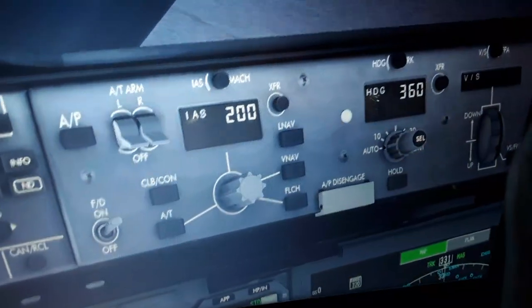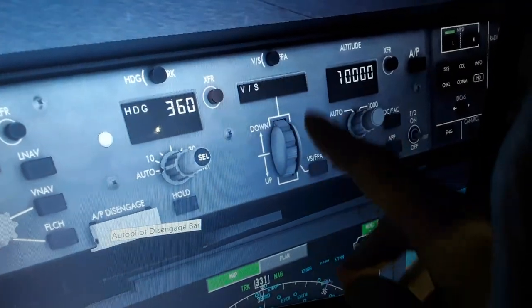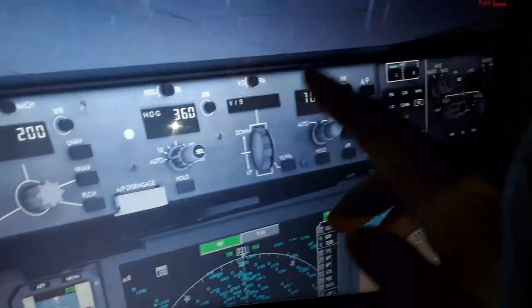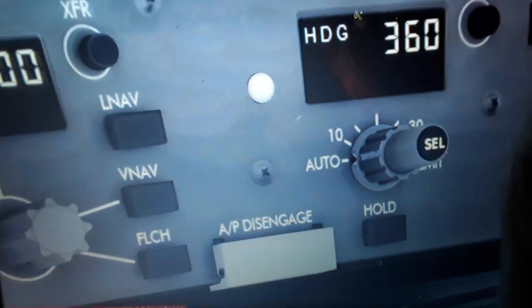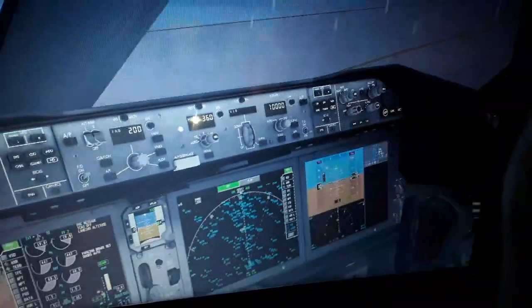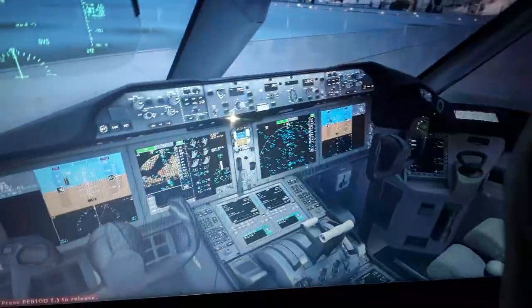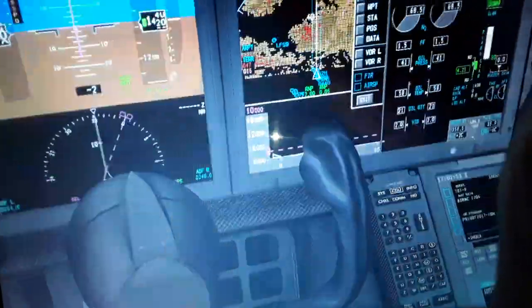We're going to select lower or higher airspeed, the heading selected, magnetic north heading, vertical rate of climb and descent, or angle of climb or descent, flight path. We have also the LNAV and the VNAV, you will see later, LNAV and VNAV connect, and the altitude over here. Also localizer and approach for autoland. So you will see also from the flight controls over here, climb and descent. So we have the horizontal trim stabilizer, the HSI here.